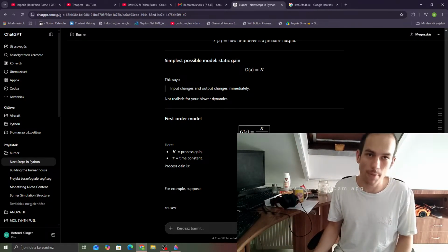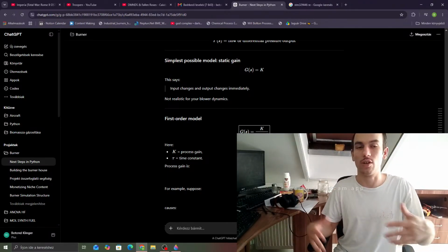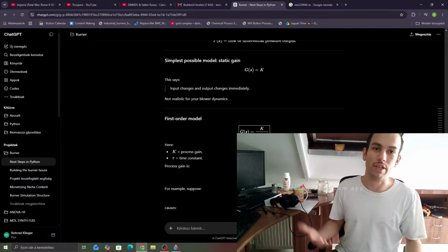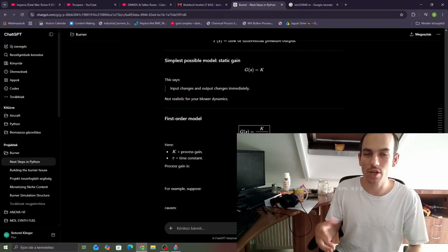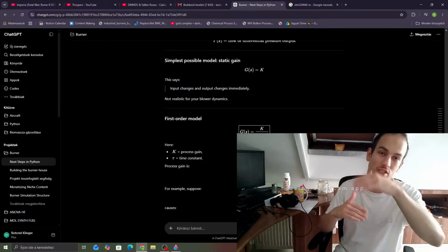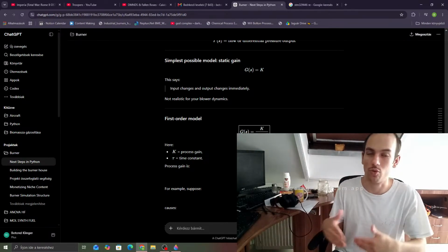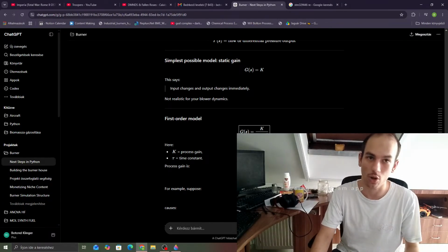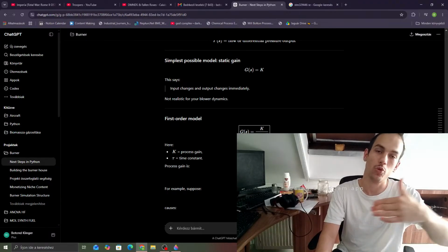So let's say you stop the thing after, I don't know, 3 or 4 days of runtime. With big plants, they usually don't shut it down every single day. Usually it's continuous, and then they have some days, or at the end of the day they shut it down so that they can do maintenance on it, so there is a range that the controller can adjust it between. Of course when it is shutting down because of some malfunction, it's not going to increase the fuel amount endlessly if it is fully clogged. But if there is a little bit of clogging, it can still push it towards the target.